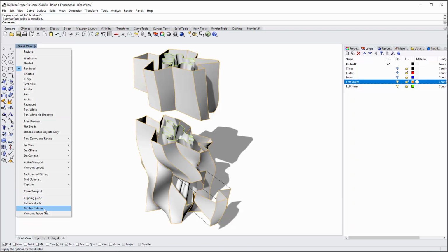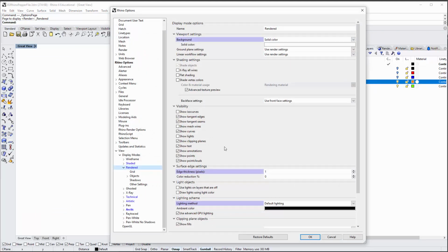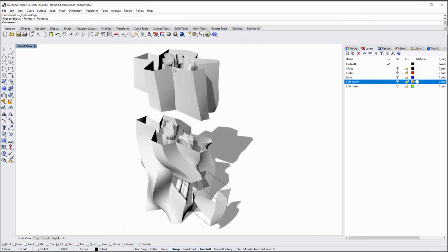The display options for this will also show whether or not the edges of things and surfaces show up. That's right here. If I bump this to 0, then those lines in my rendered view disappear. That's actually how you get those little colored lines on the edges of surfaces. That has to be activated. So yours actually should look a bit more like this.